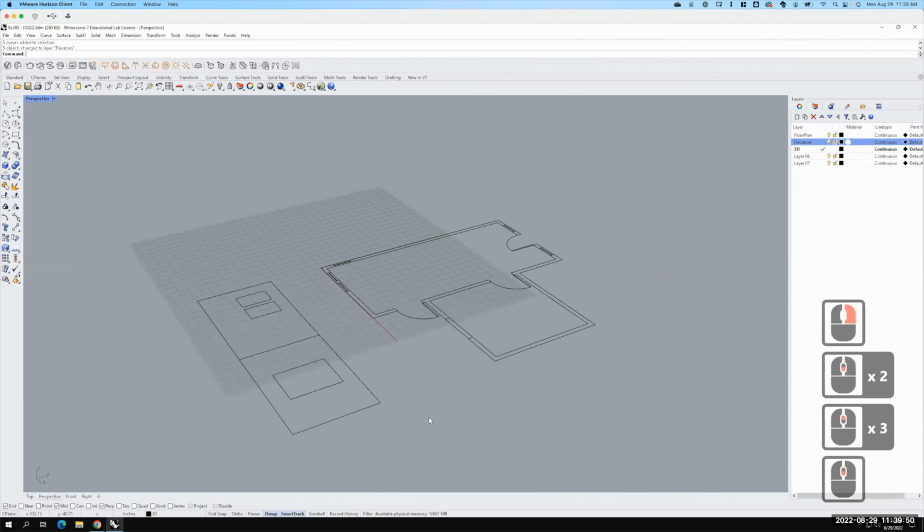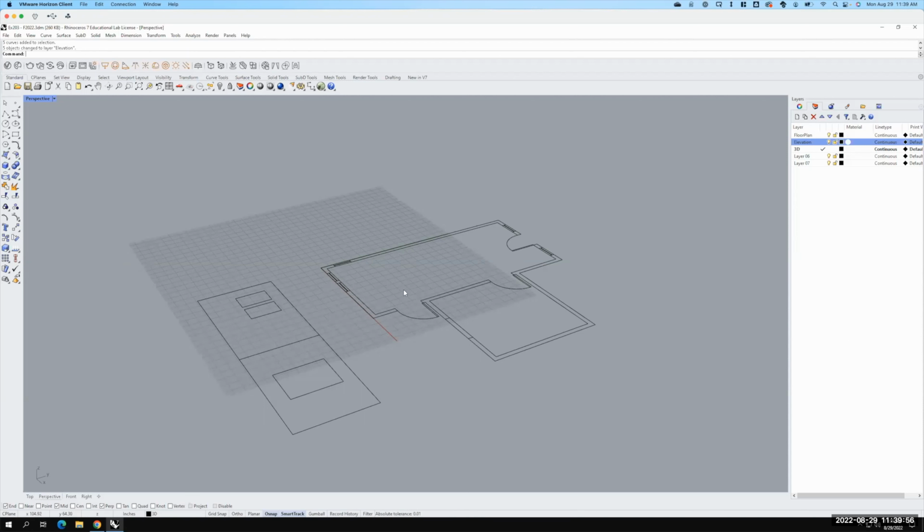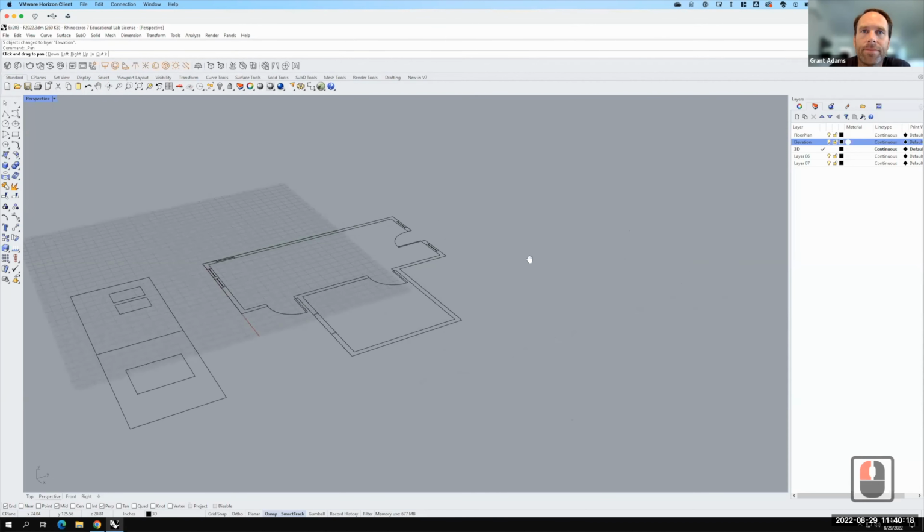Again, I highly recommend. Say that again. How can you move it from right to left instead of zoom in, zoom out? Yes. So if you want to do it, if we press the middle mouse button, do they have it there? No, you can set up a customization for that where it automatically goes to the pan. Since I don't have the middle mouse set up on the default, if you come up here into your standard tools, there's a hand icon. If you click on that, you can move it left to right.